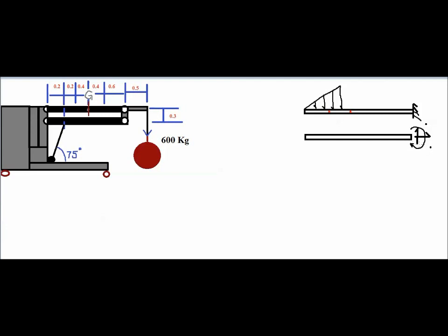So in a free body diagram, we always try to draw the reaction forces and replace all these supports, and then we draw a uniformly varying load. Okay, then what's the next step? We analyze what is the point that we need to calculate the internal loads at. If you're calculating at this point, you usually make a section at this point, just make a section there, and you analyze either of the two sections in order to find the internal loadings acting at that point.